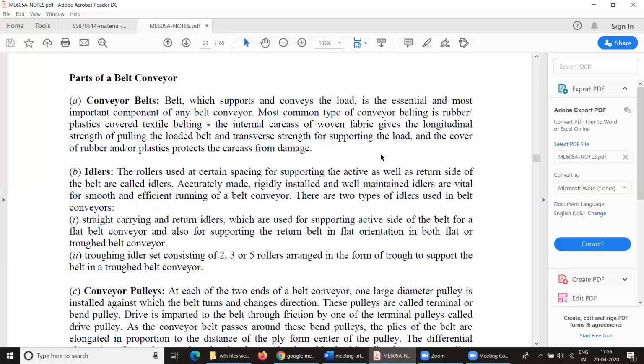The tubes of the idlers are mounted on anti-friction bearings over a fixed steel spindle. The ends of the spindles are flat machined to standardize the dimension for quick fixing in slots or in the idler structures.